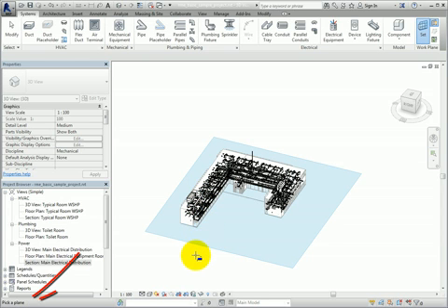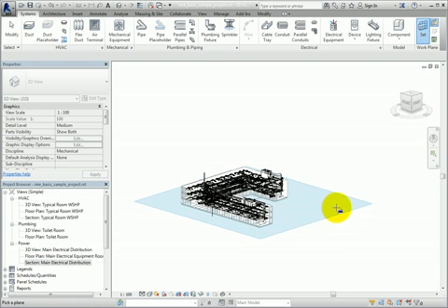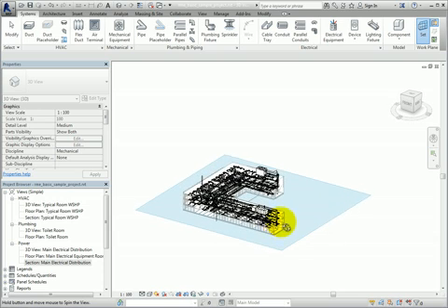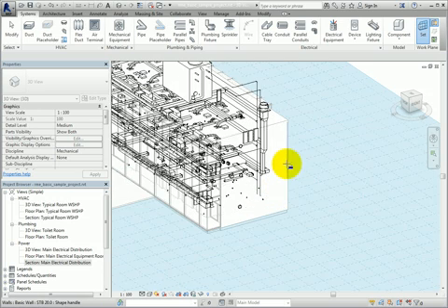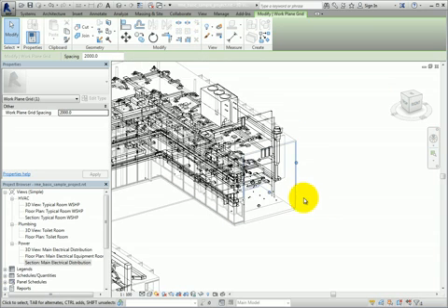Notice that in the status bar, you can see that Revit is prompting me to pick a plane. I can now select the surface of any element in the model. I'll press and hold the Shift key and the roller wheel on the mouse to orbit around the model and then pick the surface of a wall. Now, if I want, I can place elements directly in this 3D view by using the active workplane.